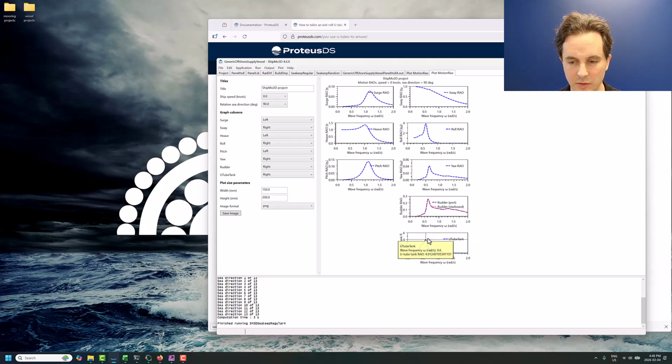That's what's happening. So yes, we have a peak here, but really what you want to do is look in the middle of the area of this curve. So this is like 0.55, instead of 0.59. So we want to go faster, higher frequency. How do we make it faster? Well, we make it faster by making the duct height a little higher.